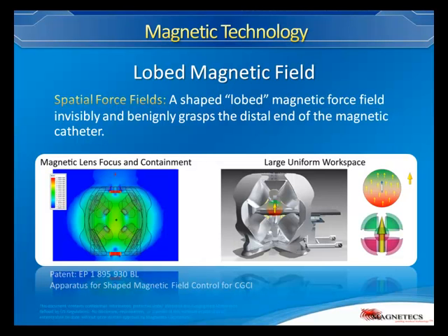As you know, when you emit approximately 25,000 Gauss in each one of the pole faces, there will be 25,000 Gauss of magnetic flux density, and here we're roughly around 1,400 Gauss. When you emit this amount of magnetic field, you will have a field that basically emanates following the inverse law and will emanate outside of this thing. The FCC mandates that you will not have more than 50 Gauss beyond 12 inches from any equipment, and it must be reduced to half a Gauss, which is the Earth's magnetic field, approximately 36 inches away from any piece of equipment.